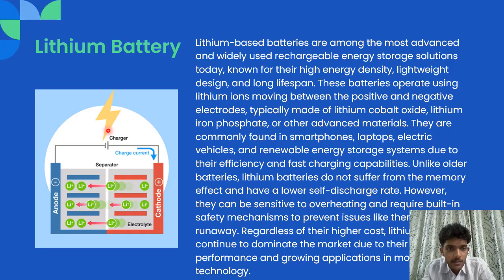Unlike older batteries, lithium batteries do not suffer from the memory effect and have a lower self-discharge rate. However, they can be sensitive to overheating and require built-in safety mechanisms to prevent issues like thermal runaway. Regardless of their higher cost, lithium batteries continue to dominate the market due to their superior performance and growing applications in modern technology.